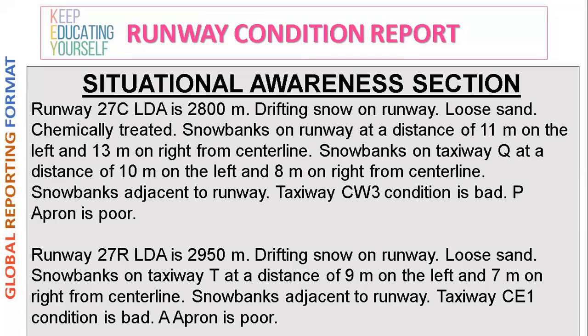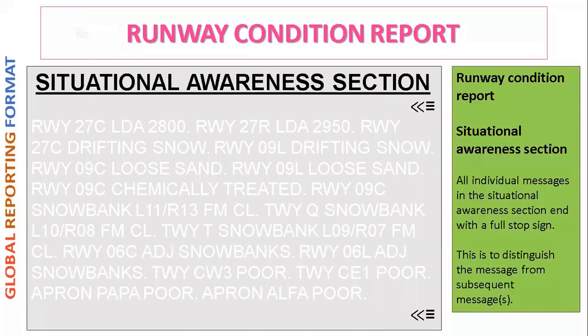He found all those things on the runway. Now he wants to prepare the situational awareness section, so we'll go one by one. In the runway condition report, I have mentioned that the situational awareness section is section 2, number 1. Number 2, all individual messages in the situational awareness section end with a full stop.